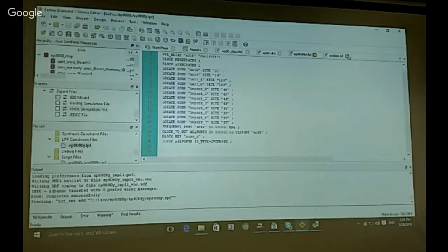But now this time we need to do the JEDEC file to produce an image for the FPGA. You have to select this. Let me see if I click this one and do the process, run all, rerun all.